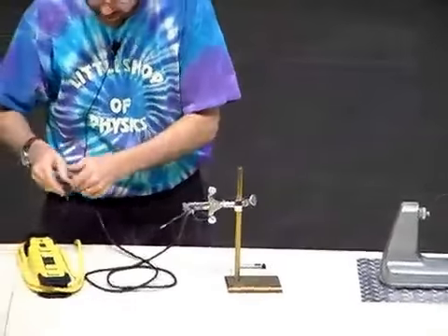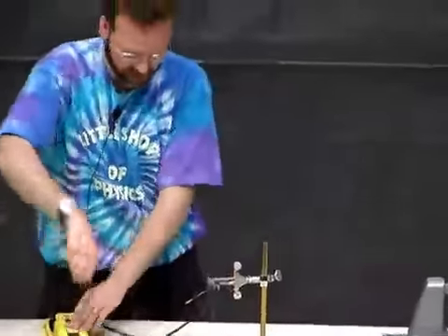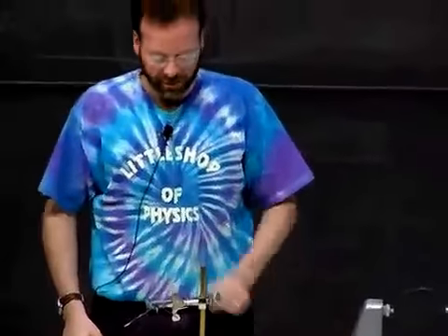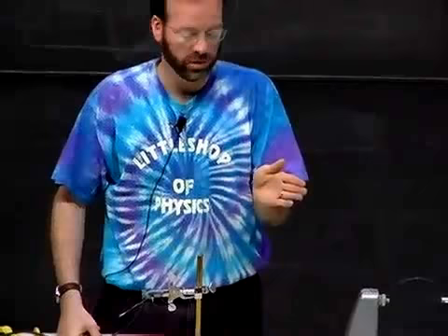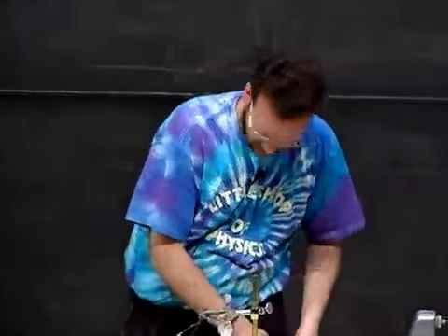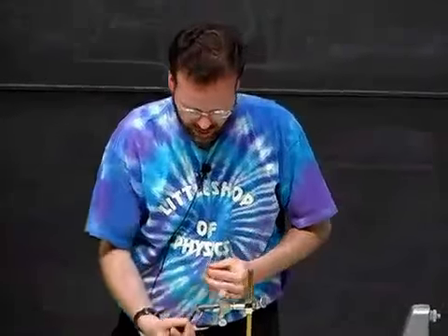If, like I said, it saw a difference in voltage. The hot was at 120 volts, and the neutral, which is connected to ground in this case, is at 0. Charge got pushed, and that's what would happen to your finger. All right, unplugged. Let's do the ground and hot.